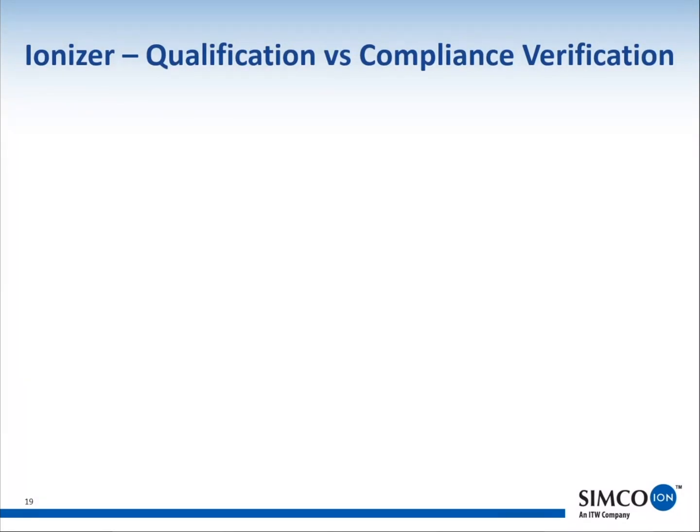So yes, I do have a question. Those require nitrogen, you mentioned? Nitrogen or CDA. You just want a clean air source on the blow-off guns. Most people use just CDA with them, and use a good filtered CDA source. Okay. Thank you.